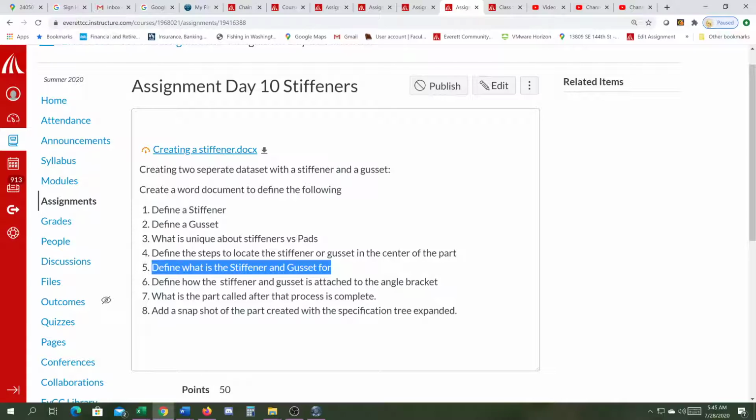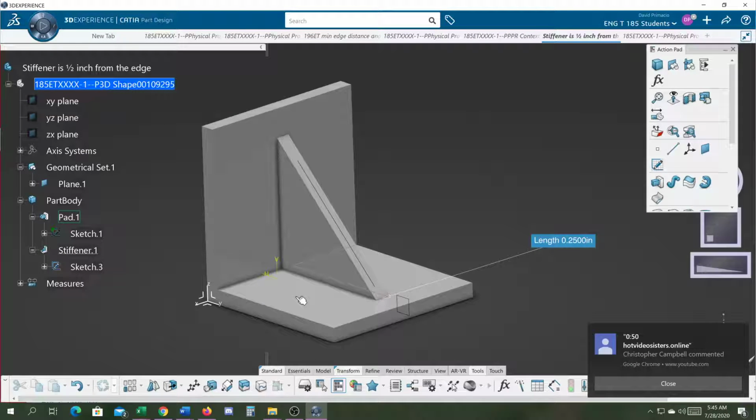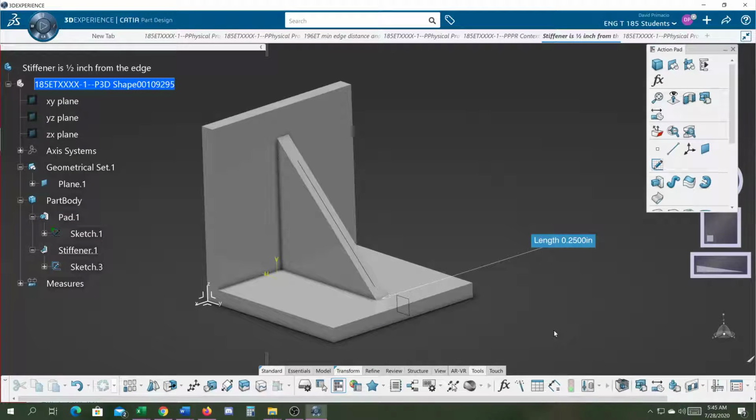So normally when I do something like this, it's not a part, it's actually called a weldment. This part would be renamed as a weldment because it's not an assembly, because I don't bolt it on, it's not a piece that comes on and off. It becomes one part in the sense that it's welded together. So this piece here in reality would be one piece, and then this L bracket would be some other piece, and we weld it here, some kind of fillet weld at the seams, making it one piece when it's done. So when you make a part like that, that's called a weldment.